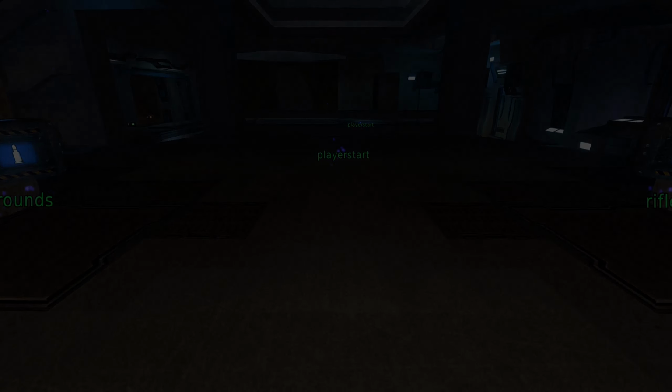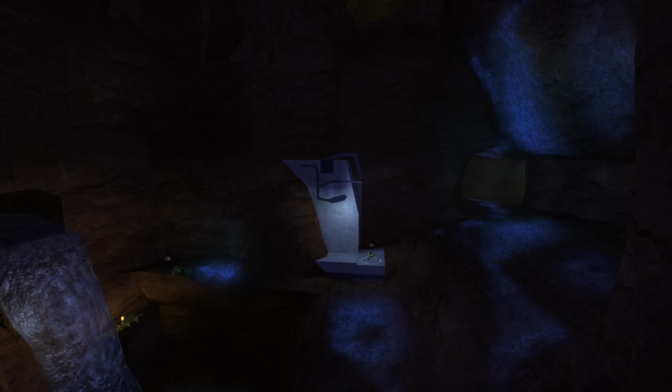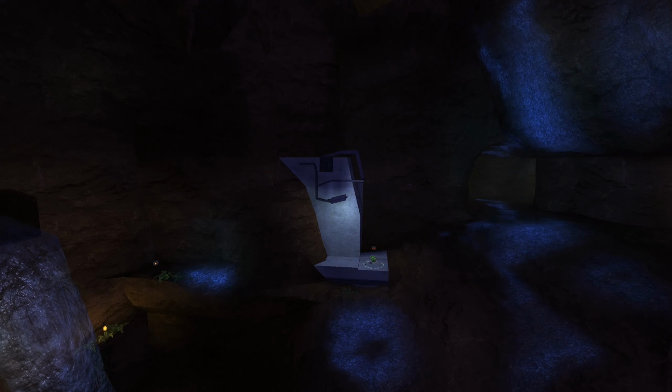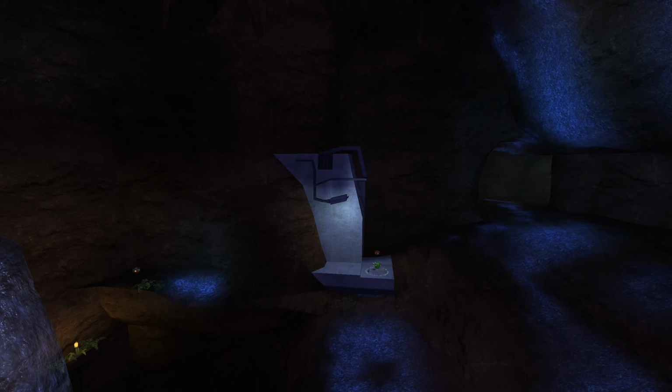As far as the shadow cast direction of dynamic shadows is concerned, sunlight only affects the rotation around the global z-axis by changing the yaw, while the pitch is always a steady 45 degrees, again concerning its direction. To update the sunlight even for dynamic shadows, we have to press K to recalculate all light maps in the scene.